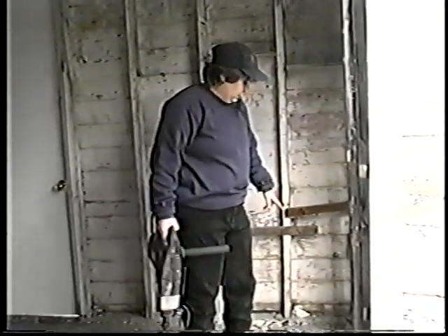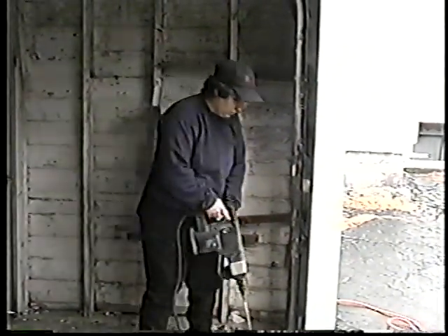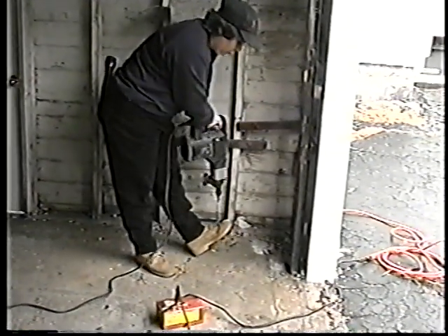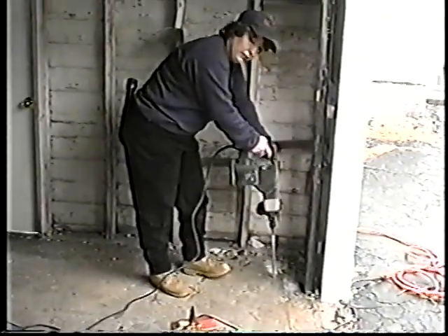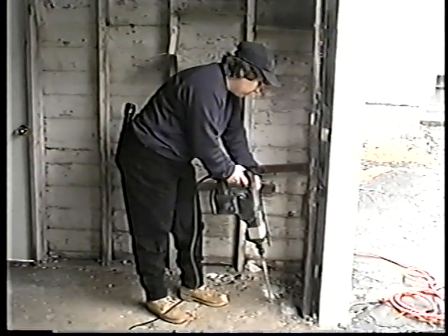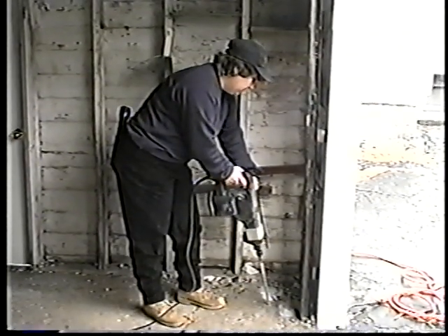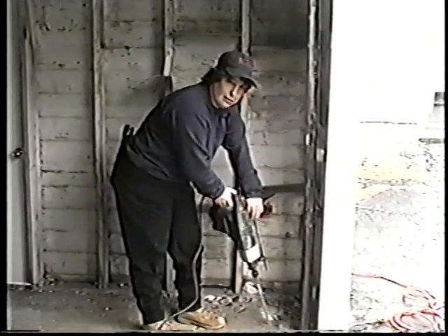This is an older structure, and what I'm finding here when I'm drilling, which is why I say things change as you do it, is this is some sort of heavier footing that's going around. So I'm going to need a longer drill bit there. And this is where they poured the lighter amount, but yet there's still something underneath. Depending on the construction, sometimes you need to drill a little more, or it's really easy to pop a hole. So I'm going to have to get another drill bit on the inside here and work a little bit more into some of these holes so that the liquid application that I put in will take.